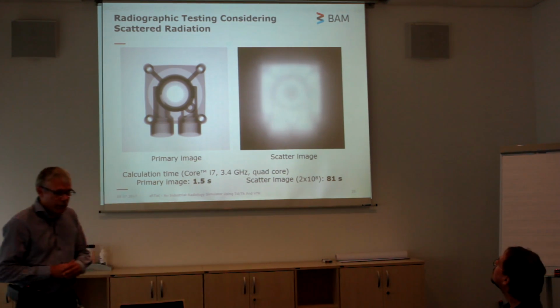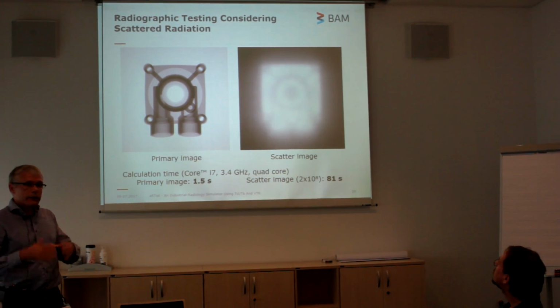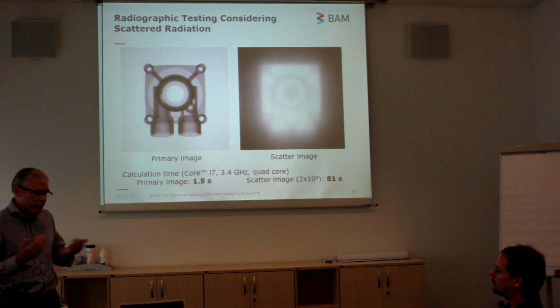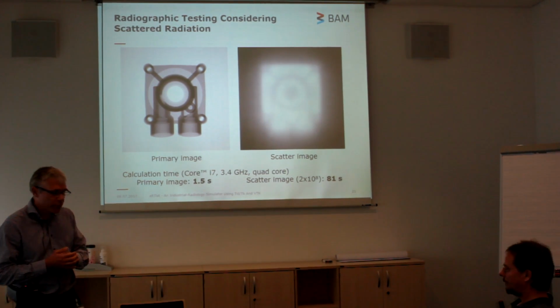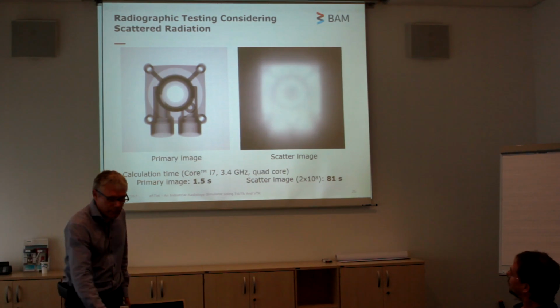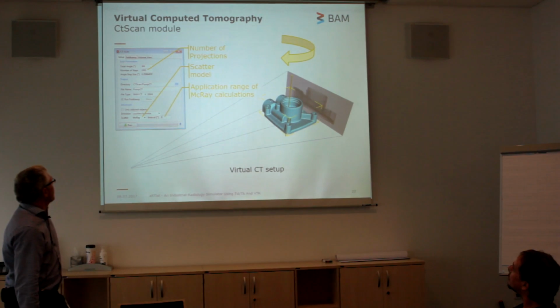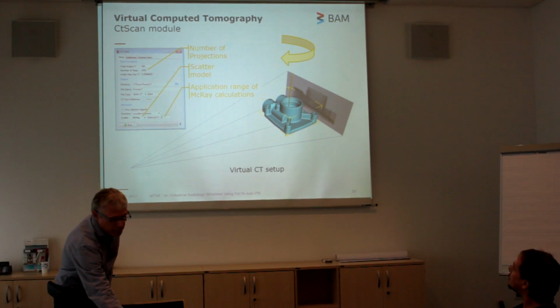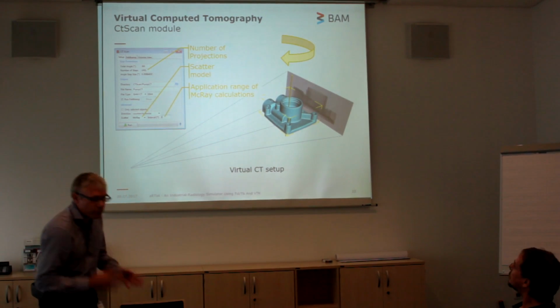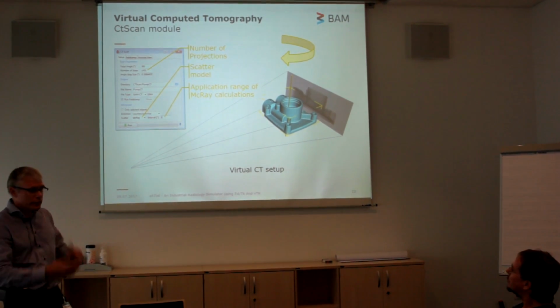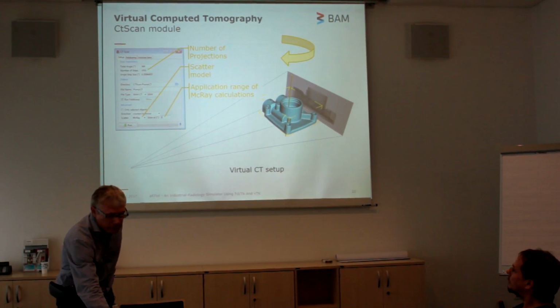And of course, we have built additional modules to automate some inspection procedures which are normal in our field. For instance, for computed tomography, you give with a few additional parameters the rotation of the object, and then the projections will be collected for different angles, and the reconstruction can be done also inside the simulator.